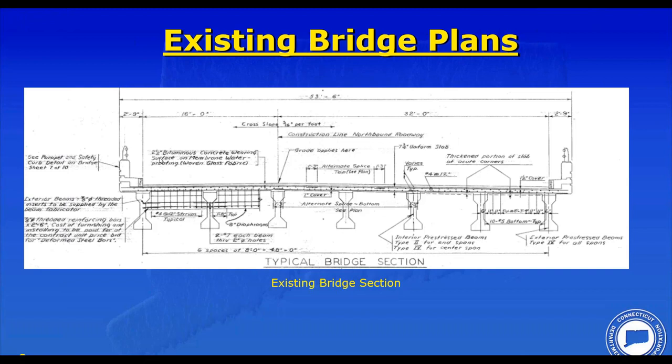The original bridge was actually built with a bituminous concrete wearing surface and a membrane waterproofing. This is what we call woven glass fabric, a very high quality membrane that was built in the 1960s, going back as far as the 60s. We have found that bridges built with these waterproofing systems perform very well. However, we have joints on this bridge, and keep that in mind.